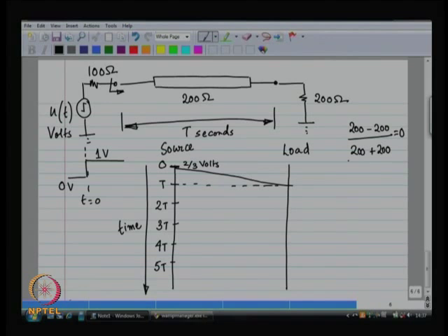Fantastic. So, nothing reflects back from the load, the entire voltage waveform is absorbed, and if nothing reflects back from the load, we do not have to worry about subsequent reflections and so on. So, the load looks like a black object, whatever you transmit it absorbs it. Fantastic.